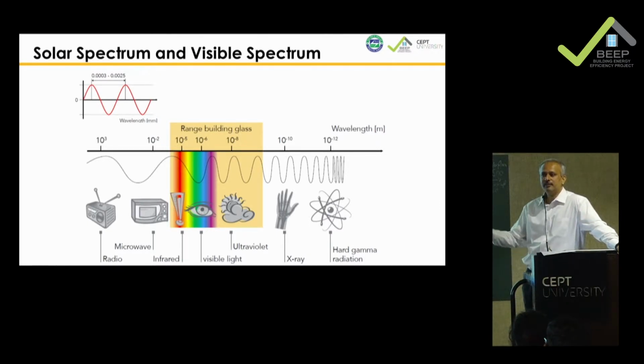But if it is a glass, the shortwave radiation changes its range, and then it cannot go out because the glass is opaque. Now, when I say glass is opaque to an architect, then what will happen to all that modernism when Mies van der Rohe and various people talked about transparency and translucency in architecture? To all go for a toss. Here we are just talking about glass being an opaque material when it comes to the infrared range. So infrared radiation or infrared rays cannot pass through glass, and hence we call glass an opaque material when it comes to infrared. Okay?